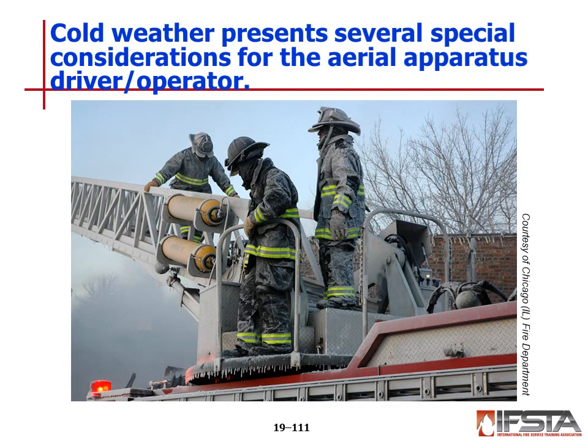Cold weather presents several special considerations for aerial driver operators. It causes an increased viscosity of the hydraulic oil, slowing the overall machine operation. Less obvious effects of cold weather include physical changes in the properties of the metal structural members of the device. When subject to extreme cold or sub-zero temperatures, the device should be operated in a manner that will minimize or eliminate shock loading to its structural members.